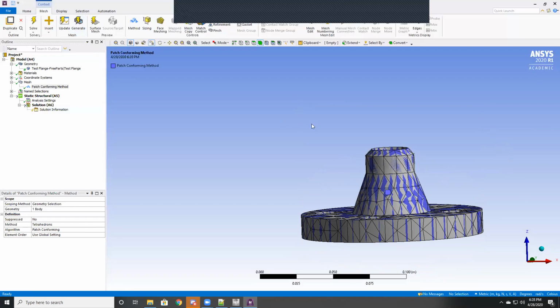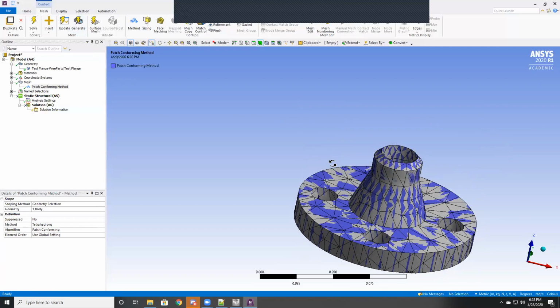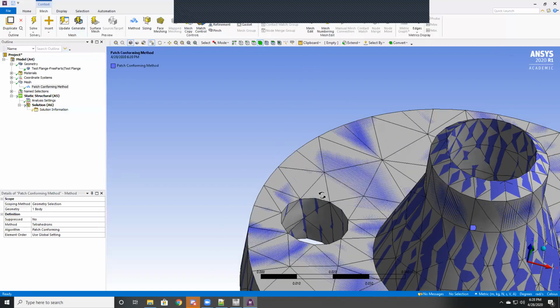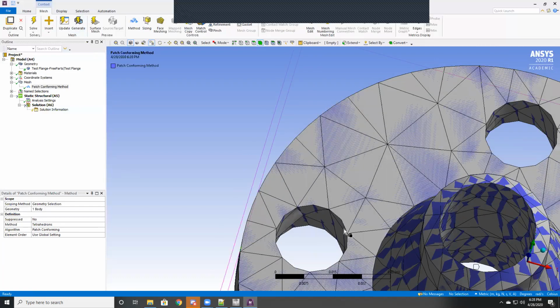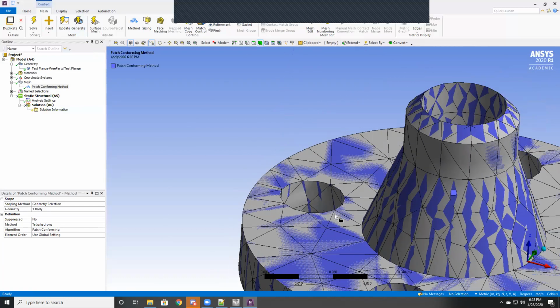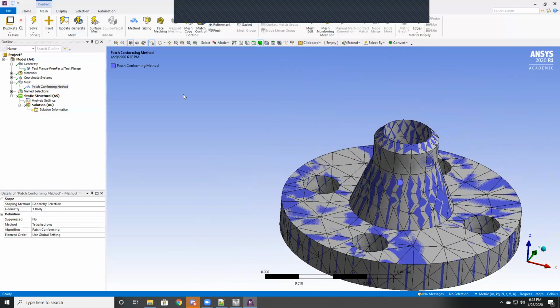The next thing to note is that a lot of these cells are very big, and that's a big part of what's losing us the quality of these circles. So there's a few ways to do it. One is a refinement. A refinement will basically take a surface or edge and force that to have more detail. So if we really, really wanted the detail in those, then we could set a refinement and it would make a lot of smaller cells near that edge.